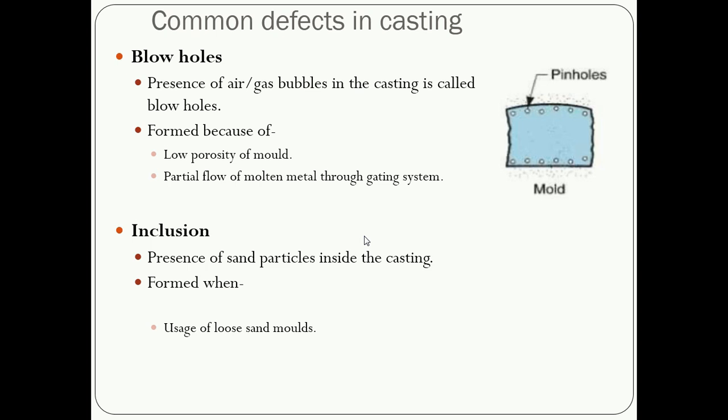Skill is required while removing the pattern, and utmost care we have to take that there should not be a formation of a single loose sand particle. Otherwise this inclusion defect will come in the casting, and which needs to be removed or repaired.